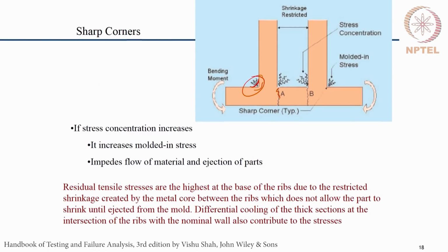Because of sharp corner radiuses, the part ejection from the mold can also be a problem. So, one of the important design considerations is to avoid such corners.